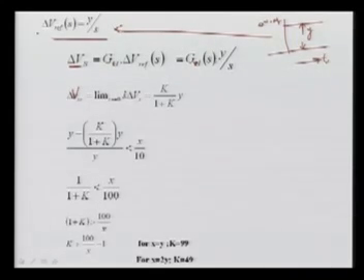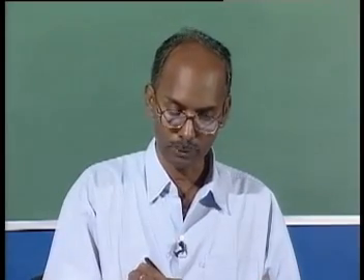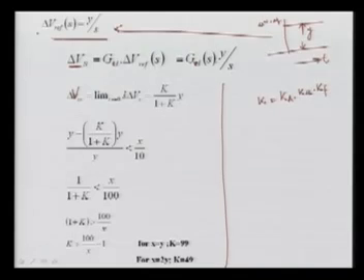Now our Ka into Ke into Kf, let's suppose, I take as K value. So what we are getting now, the closed loop transfer function will be, before coming here, how I got it, we require this Vs in terms of these values. You remember this is your GCL, which is nothing but G(s) over 1 plus G(s).